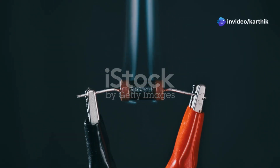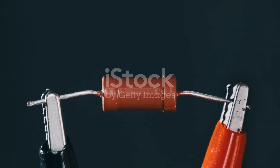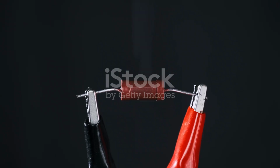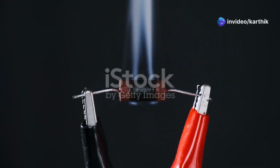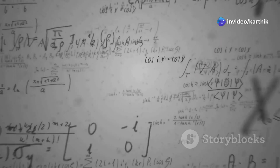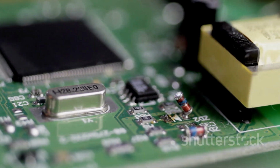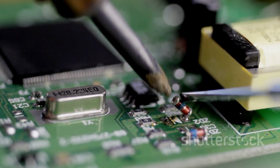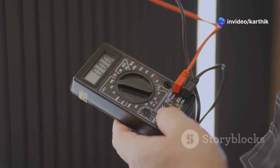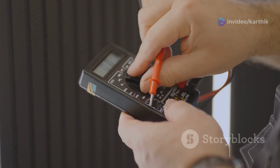Section 4: Resistors and Energy Dissipation, the importance of staying cool. When current flows through a resistor, some electrical energy is converted into heat. This process is called Joule heating or ohmic heating. The amount of power dissipated as heat is given by P equals I squared times R, where P is the power dissipated in watts, I is the current in amperes, and R is the resistance in ohms. This equation shows that power dissipation increases with the square of the current and increases linearly with resistance.